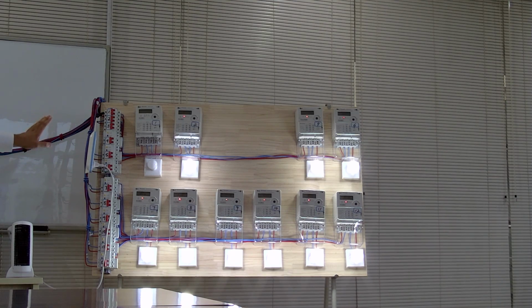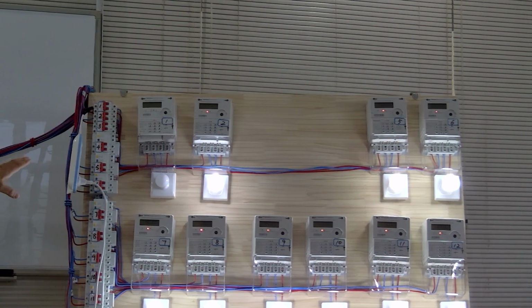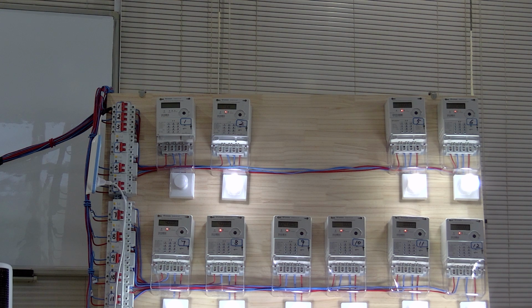We didn't touch meter number 1. Meter number 1 is untouched, even though it's off. But immediately after turning on, I will show you the credit on meter number 1, and you will see that meter number 1 credit is untouched. It is unchanged, and it's still 2 RMB. That's because meter number 1 cannot measure consumption on the heater, which is an illegal load.